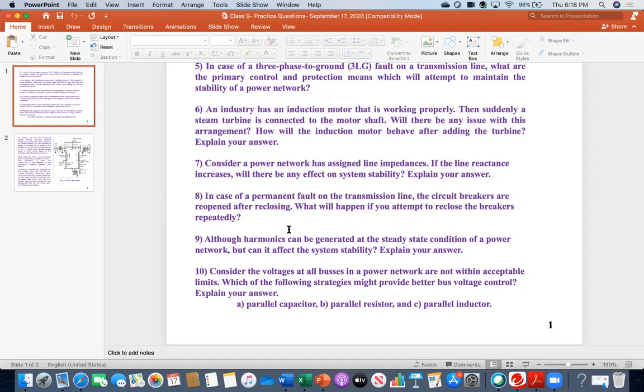The frequency of the grid. No, the frequency of the grid will affect what? If you think about the impedances, will it impact the resistance or will it impact the reactance? Reactance part. Exactly. So therefore, everybody see, as you know, harmonics means a multiple of the fundamental frequency, not 60 hertz, like 120 hertz, 180 hertz, or even higher. Resistance is independent of frequency, you know. But think about the reactance X. What is X? Like XL, inductive reactance, 2 pi FL. So therefore, inductive reactance is related to frequency. Therefore, your reactance is getting high.